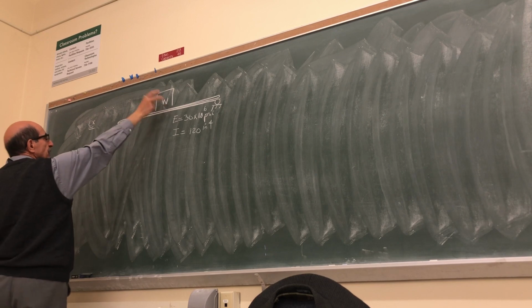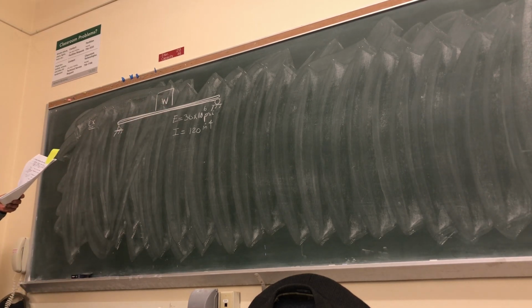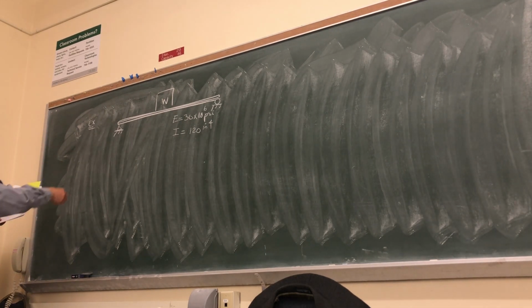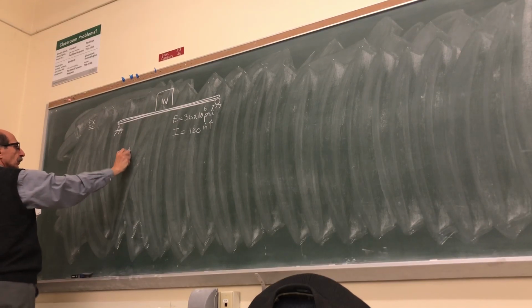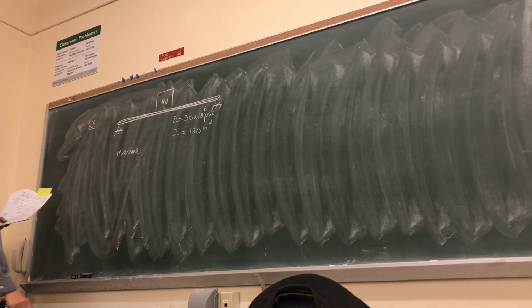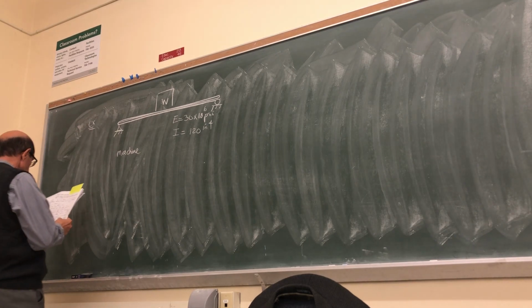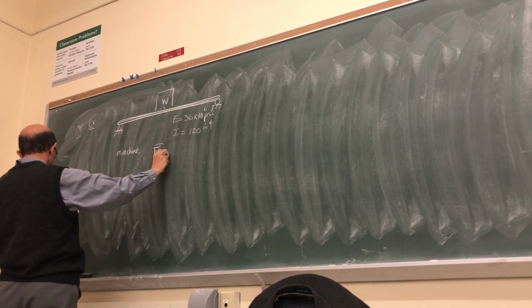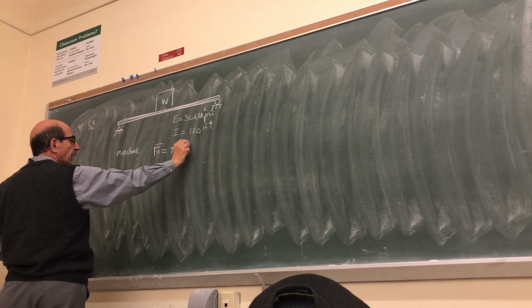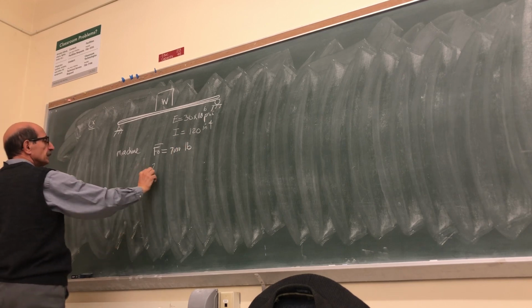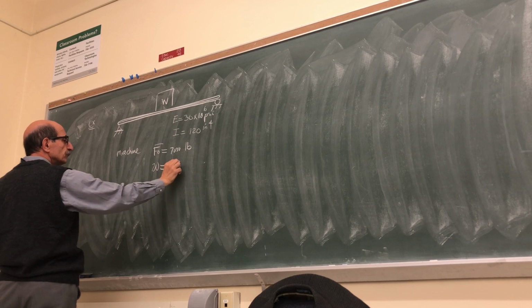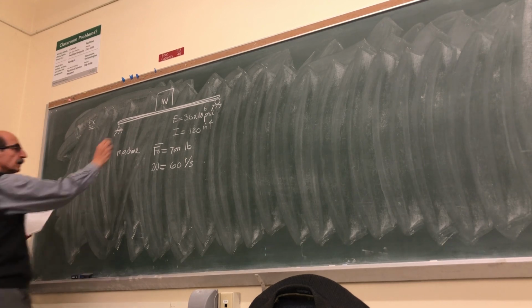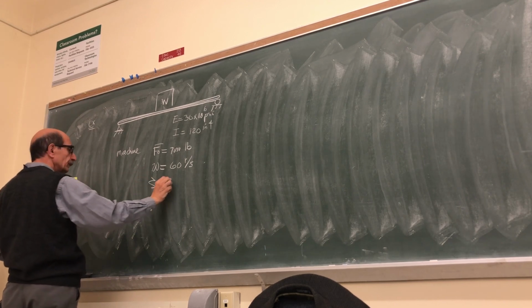So the system sitting on this beam is basically a machine that has a piston going up and down. The machine generates a harmonic force whose amplitude is 7,000 pounds, and operates at a frequency of 60 radians per second, okay? Let's say the system also has a damping of 10%.